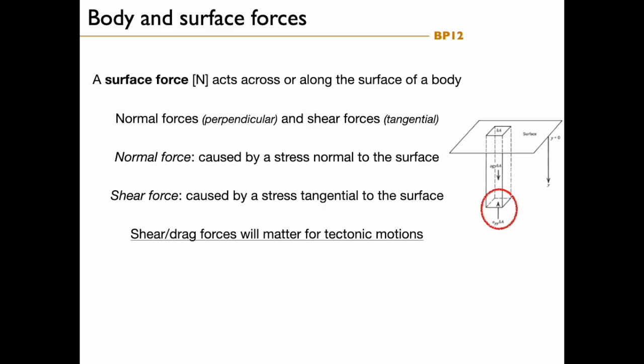A surface force is a force that acts across or along the surface of a body. There are normal forces, those that are normal, perpendicular, and shear forces, those that are tangential. The normal force is caused by a stress, which is normal to a surface. So remember the example of last time. The normal force here is related to the product of the normal stress, sigma yy, times the surface, delta A. It is the normal force in reaction to the body force here. The balance of these two forces will create equilibrium.